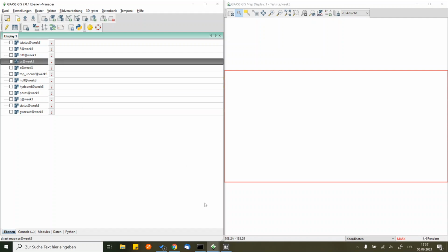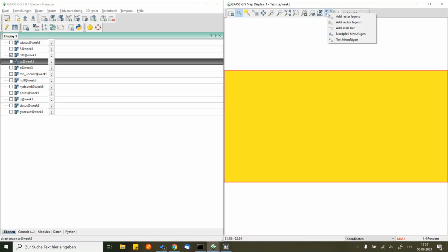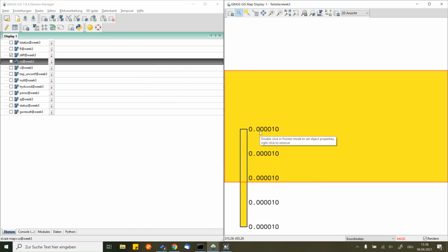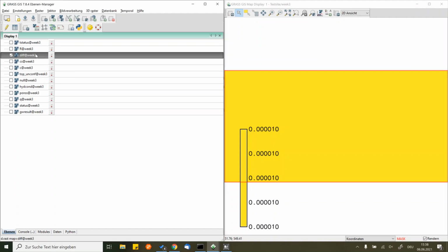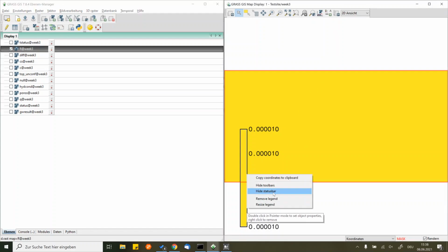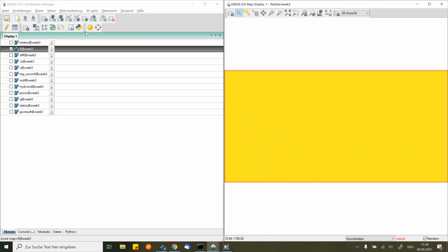I uploaded something from another old example of mine, just to give you a list of all the parameters you need, but we will simply use the null vector for that. We need to provide diffusivity values. And here you see I took a homogeneous distribution of a value of 0.00001 for the diffusivity. We also need to define a retardation vector. I put that one simply to 1. So we will not have any retardation effects here.